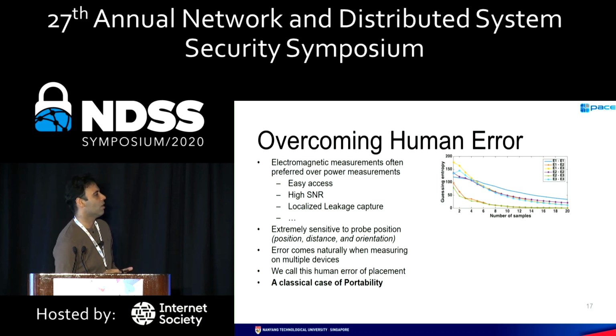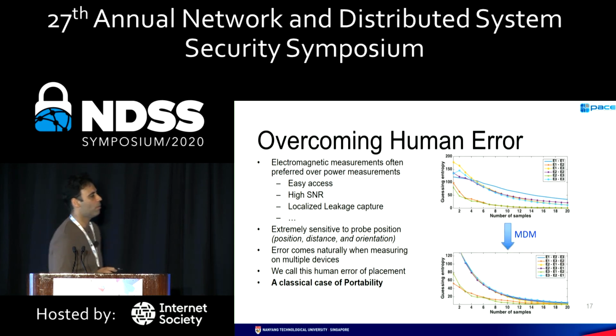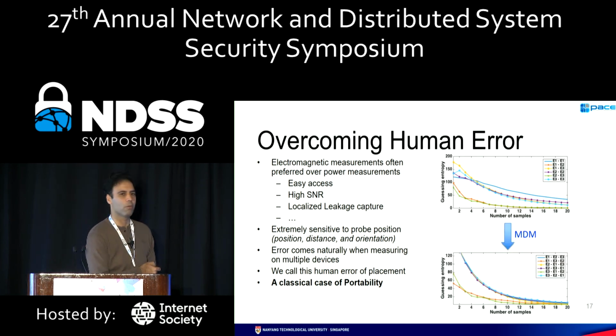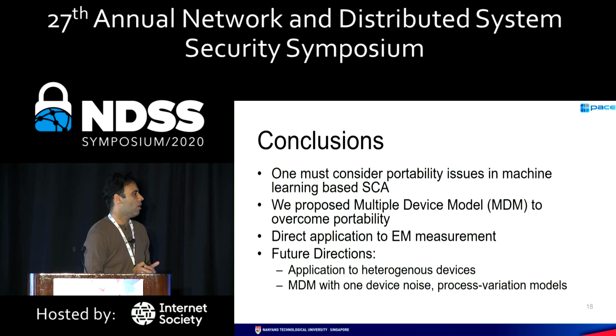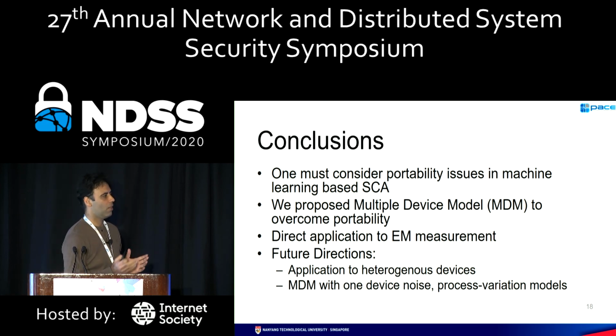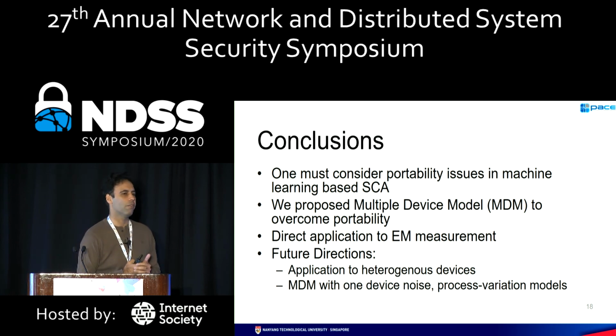And actually, when we look at this problem and try to apply the MDM model that was previously proposed, we see that when you learn on multiple EM placements on the same device, you can attack it much more easily. Therefore, coming to the conclusion, portability is an issue when we are looking at profiled attacks, especially with machine learning techniques, and we should take that into account. Otherwise, the evaluation or the security certification we are doing can be misleading.